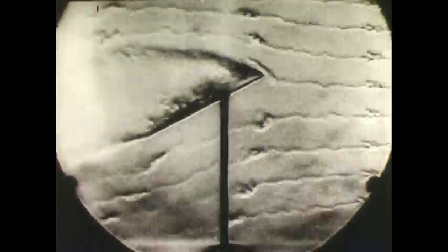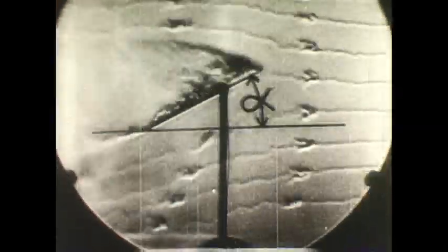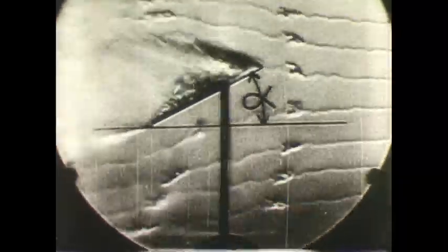Placing a flat plate in the visible stream, we observe a physical demonstration of the turbulence previously shown graphically. Turbulence in the wake on the upper surface of the plate is now made visible by means of fine wires electrically heated. The symbol alpha indicates the angle of attack. The seemingly reduced airspeed is now about 1/100th of the actual airspeed. Air flows past the plate above and below, leaving a wide turbulent wake behind.